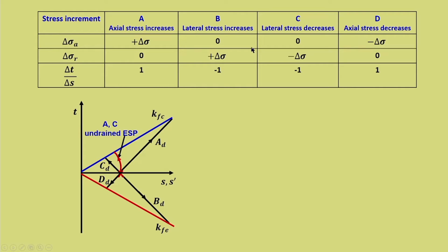So, this is the undrained stress path for A and C. Why is it written A and C? Because that represents the compression, and the effective stress path for cases B and D, which represent extension, is given by this. Now, where does it go and fail? That is governed by the A value. If, after substitution, 1 by 1 minus 2A is the slope of the effective stress path, then depending upon the A value, you can decide in which direction the effective stress path goes.